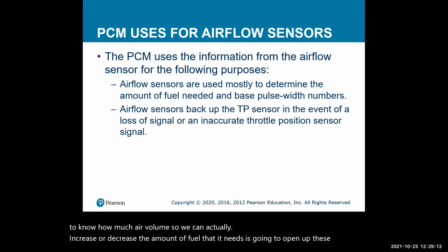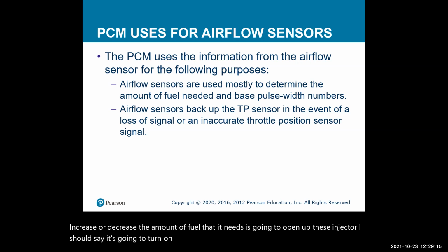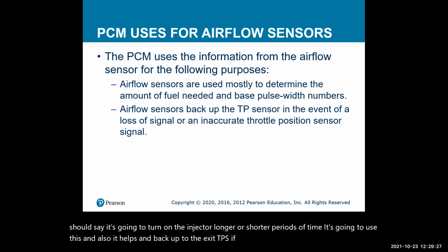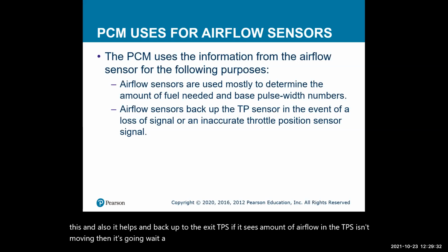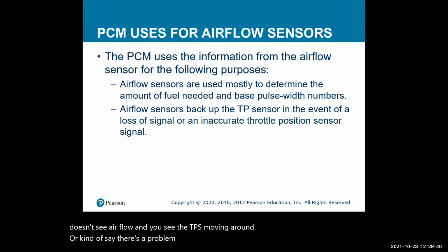It's going to turn on the injector for longer or shorter periods of time. It's going to use this, and it also helps as a backup to the actual TPS. If it sees airflow and the TPS isn't moving, then it says, wait a minute, we've got a problem here. Or vice versa: if it doesn't see airflow and the TPS is moving around, there's a problem here, Houston, we need to diagnose it.